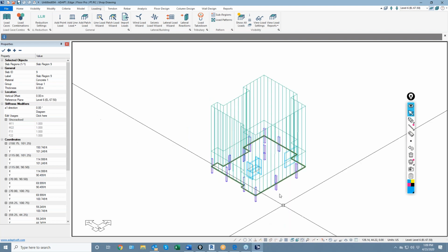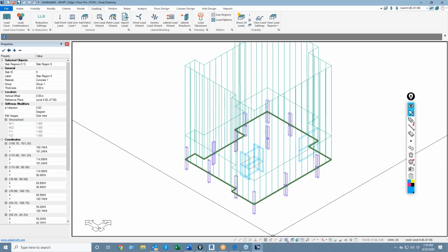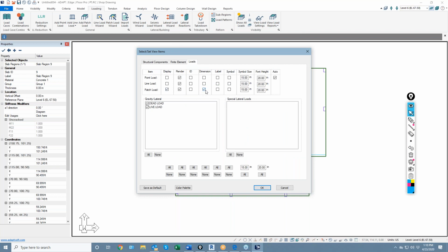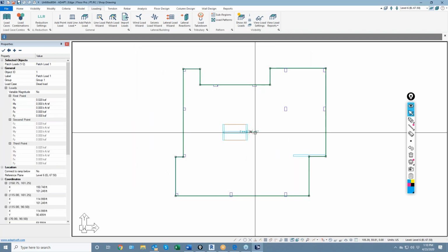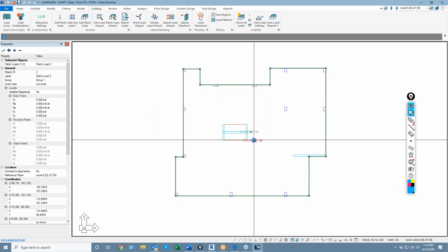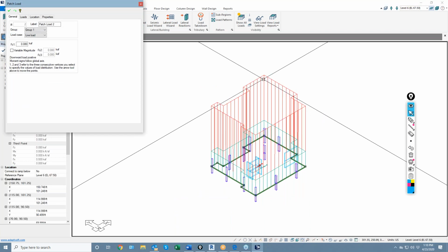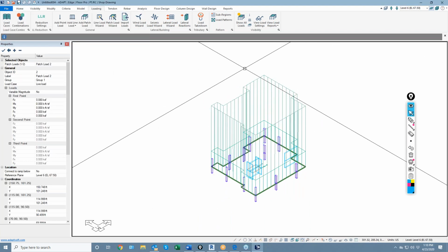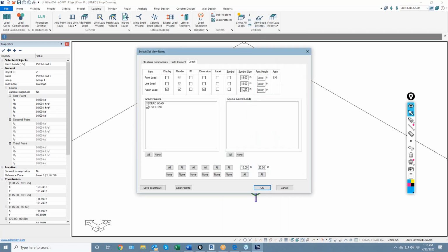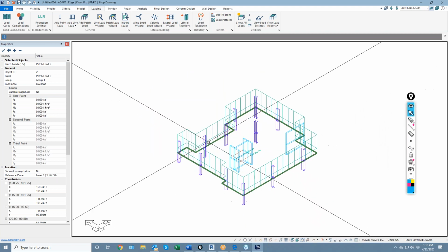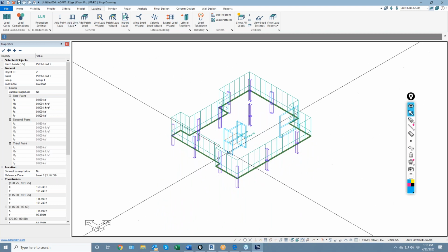And the loading, just very quickly, visibility-wise, it's hard to see in this view unless you come over here to the loading visibility panel, and we can go ahead and turn on, for example, the dimension of the loads, and then we can see those two loads are added and toggle between them, selecting that. From this perspective, we can see the loads clearly. If you don't like the height of that load symbol, we can change that, just change the symbol size here for the patch load. Patch load is the same as uniform load or distributed load in the model. So we have some loading there.